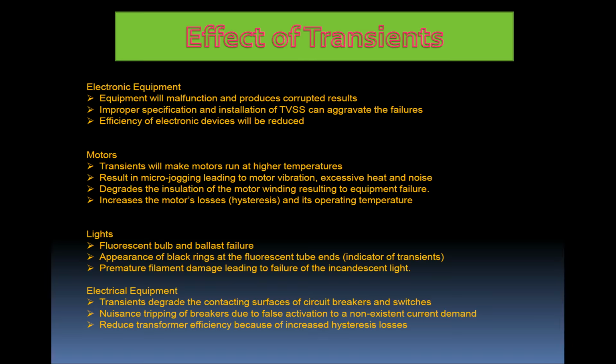Other than that, our motors will run at high temperature. Over time, they will fail. Micro jogging, motor vibrations, excessive heat, noises. It degrades our insulation. So this is something that we have to think about, because when our motor windings have insulation degradation over time, they can fail. We also have hysteresis losses due to transients, and temperature rise due to transients.